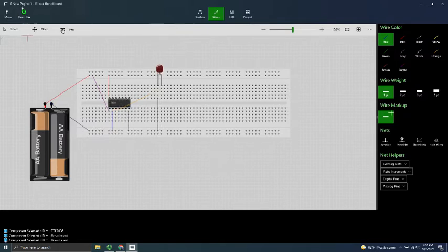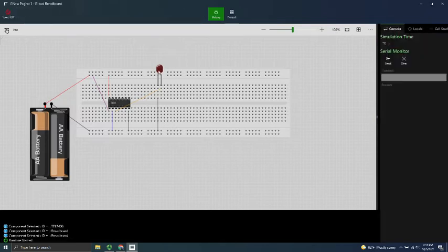Let's go ahead and run the circuit by hitting the power here. And what happened? Nothing. Because we have a high, or what is this? 1.5, about 3 volts, a little about 3 volts here, and we have 0 volts here. But we need 3 and 3. We need 2 high voltages, or 2 highs, or 2 ones, and pin 1 and pin 2 for this thing to turn on. So let's go ahead and remove this and move it to the positive side.